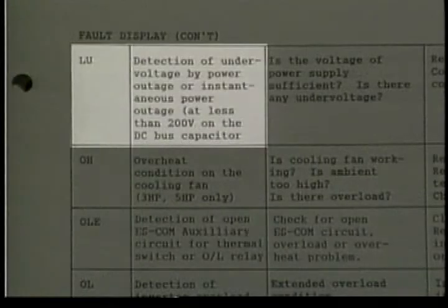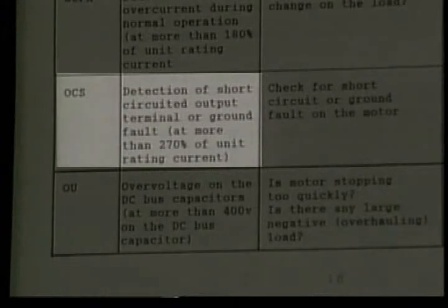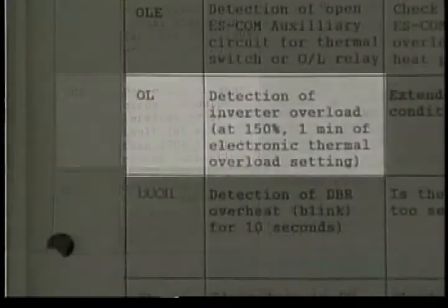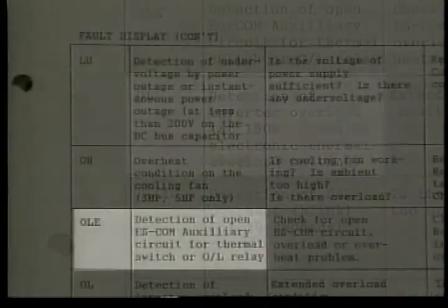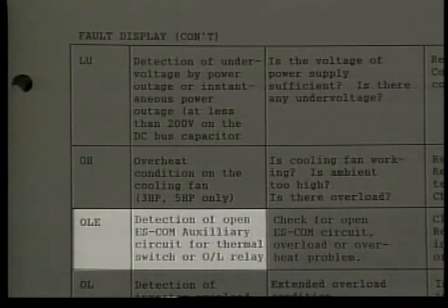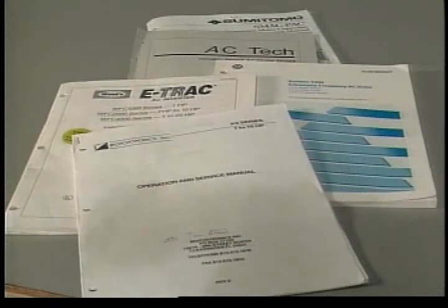This inverter displays one code to indicate that the input voltage was too low. It displays a different code if the motor has shorted out, and still another if the motor overloaded while it was running. And another code indicates when electrical interference may be garbling input signals from field devices such as limit switches or photosensors. If you're not familiar with what the fault codes mean on the inverters in your facility, refer to the operator's manual provided by the manufacturer.